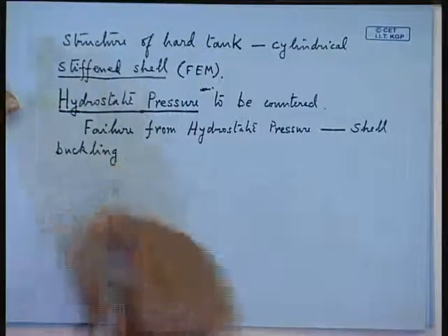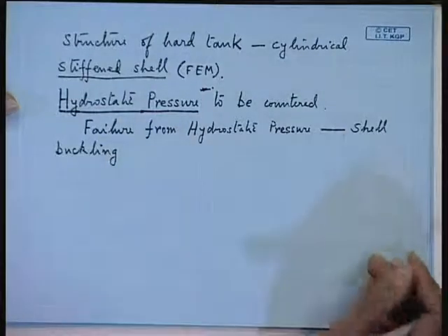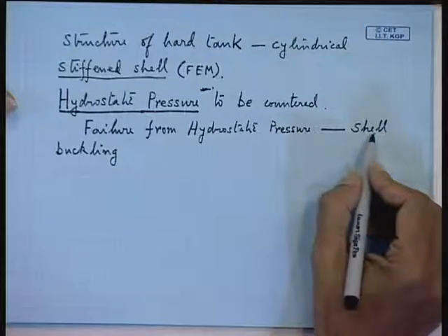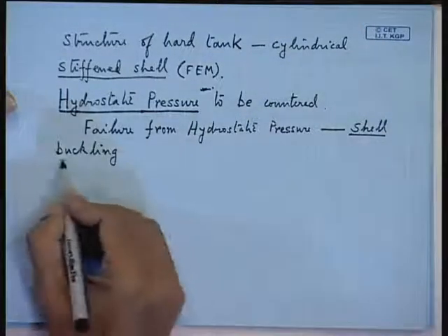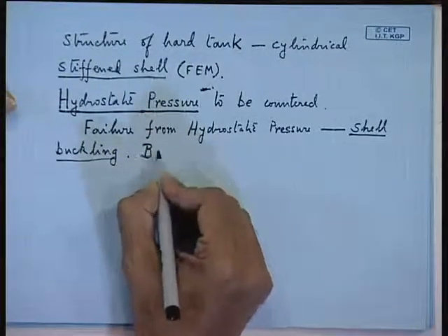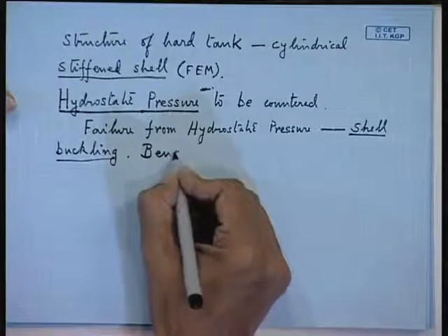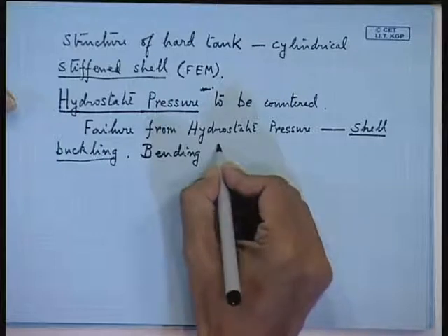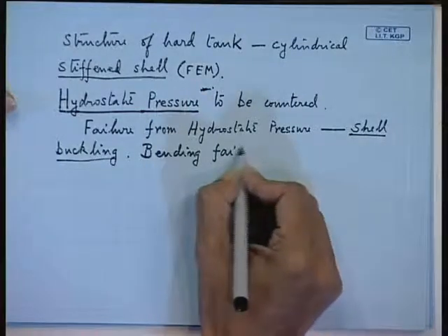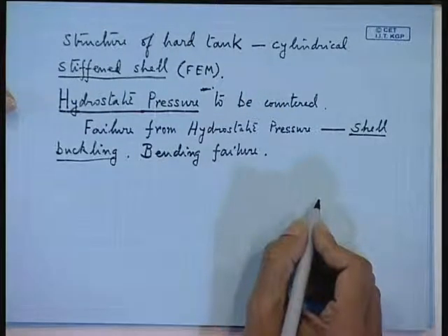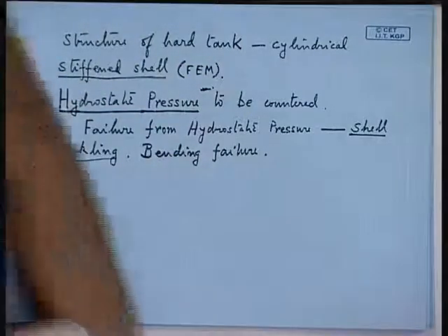What are the mechanics in shell buckling? Normally I will try to give you some idea in your offshore technology class. So, shell buckling is prevalent. The other part is bending failure because of the length. So, bending and buckling are the prime failure modes of this type of structure, because of the length of the structure.